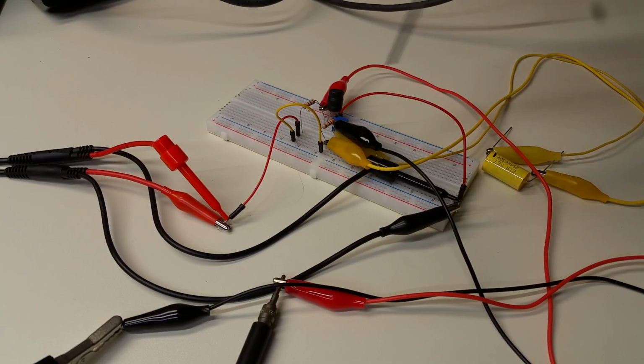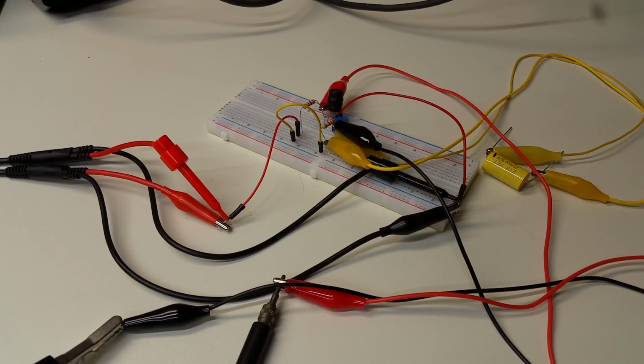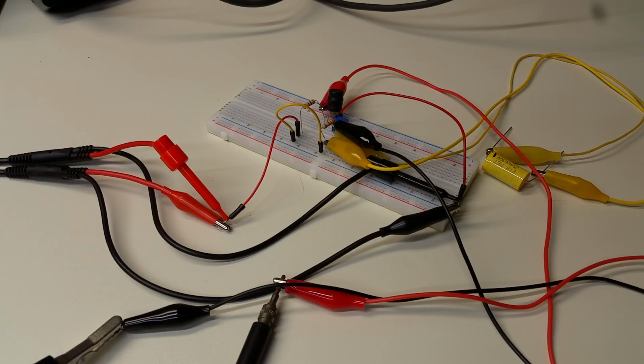And so what I'm going to do is adjust this potentiometer backwards and forwards, and look for a null, and then I will take the potentiometer out of the circuit, measure what resistance I stopped at, and then use those values to compute the value of L. Let me just stop this for a moment and use a bridge circuit to diagnose the bridge circuit. I'm going to use a vacuum tube voltmeter because the analog swing of the meter is really nice for identifying nulls. And we'll be right back. Here we are.